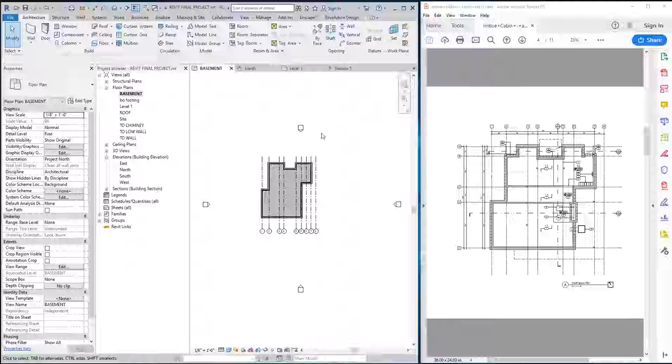So I also could have created a second wall type and called it furring wall or something, and it would have just been a stud with gypsum board on one side. And I could have just drawn it on the inside of that, right? But the problem with that is that they're not connected. So if I ever had to move the exterior wall, I would have to adjust both wall types on the inside to make it work. So this makes it easy.